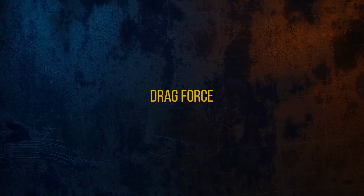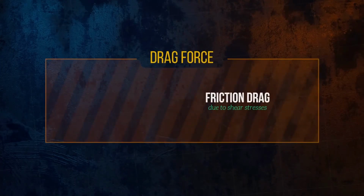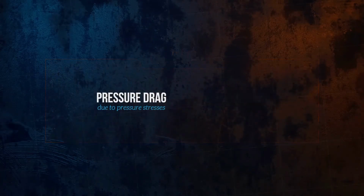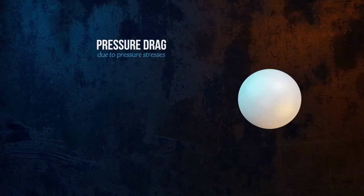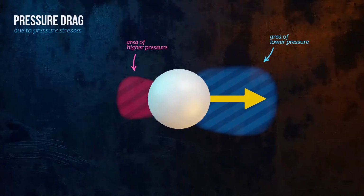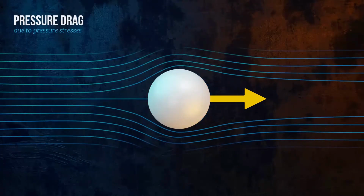First, it is drag. The component of drag caused by the shear stresses is called friction drag, and the component caused by the pressure stresses is called pressure drag or form drag. Pressure drag is most significant for blunt bodies like this sphere. It is essentially caused by a difference in pressure between the front and the rear of an object. Pressure drag increases significantly if flow separation occurs, which is when the fluid boundary layer detaches from the body, creating a wake of recirculating flow.